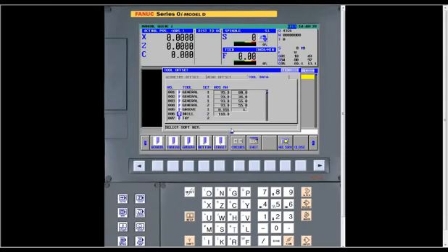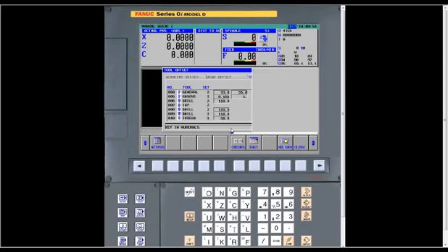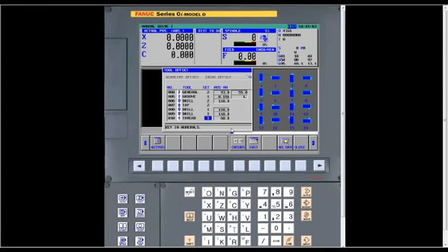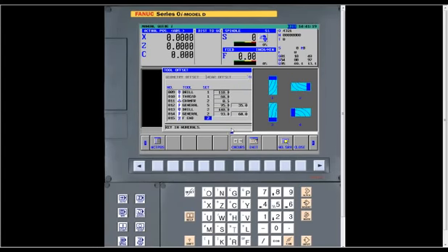In a tap, you don't have to put a lot of information, just the tool type has to be correct, and then the orientation. On a horizontal lathe, it's typically going to be a number 2 for the left spindle. Then for threading, you don't have to put a lot of information, just the right tool type. Again, the setting based on what your tool looks like, and then the angle on your insert. Very simple. But it's critical that you get this information correct beforehand. And a chamfer tool, general, and then a flat end mill, again, just the orientation.